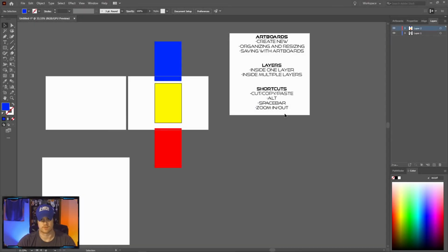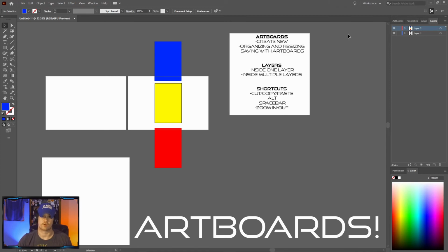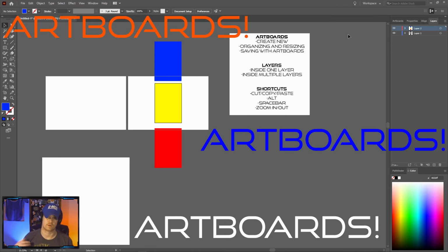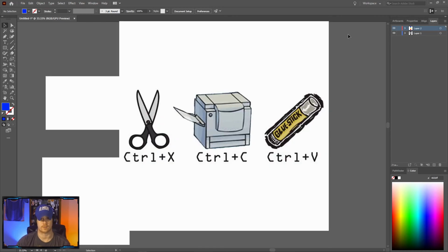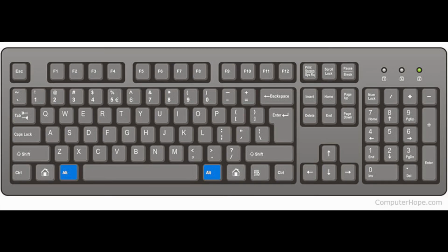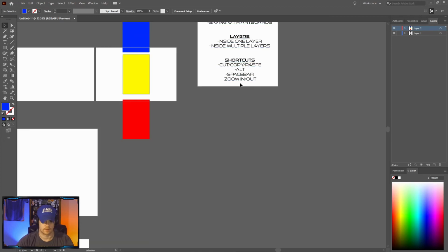I hope everybody got something out of this. We went over artboards, how to create new artboards, save artboards, and organize artboards. We went over how to work inside of one layer. We also worked inside of multiple layers. And I also taught you a few shortcuts that can help you with your workflow. So we have cut, copy, and paste. We have Alt, which is a copy tool. Spacebar, which helps you move around. And we also went over zoom in and zoom out, which is Control plus and minus.